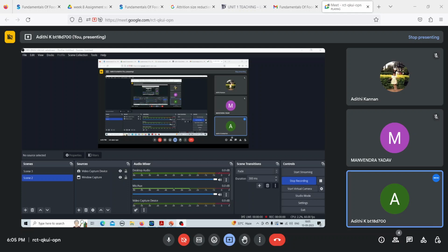So now the sphericity is equal to surface area of the sphere divided by surface area of the particle. So 346.19 millimeter square divided by surface area of the particle, 401.92 millimeter square. If you divide both of it, you get sphericity as 0.86. Answer is option A. Any doubt in this?